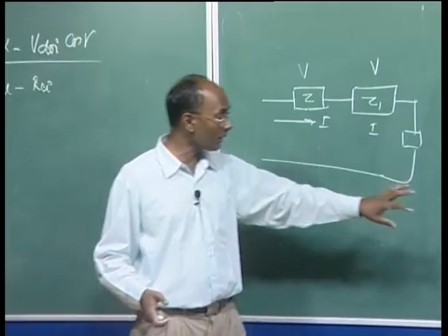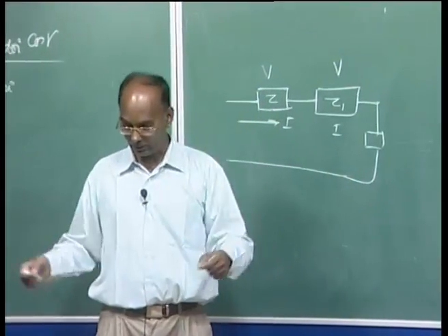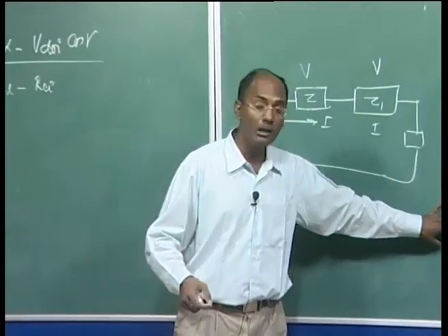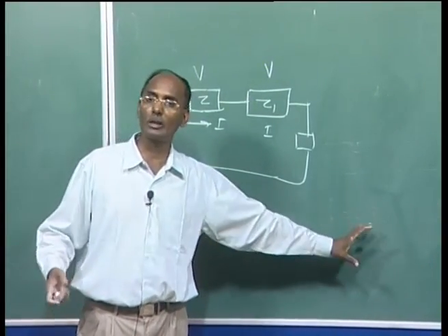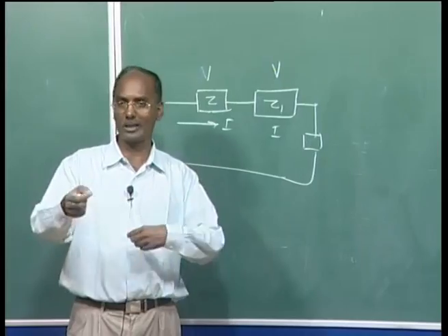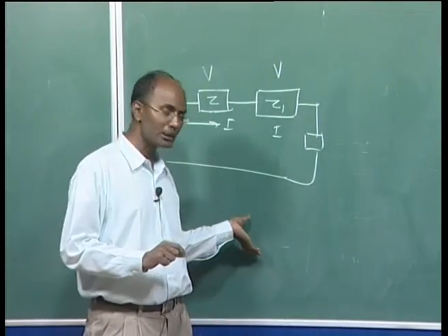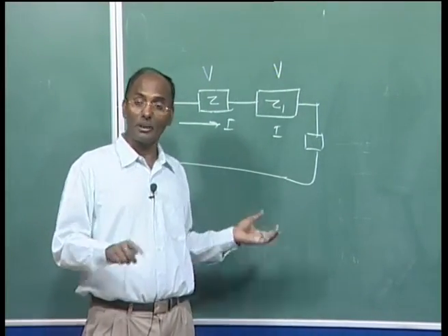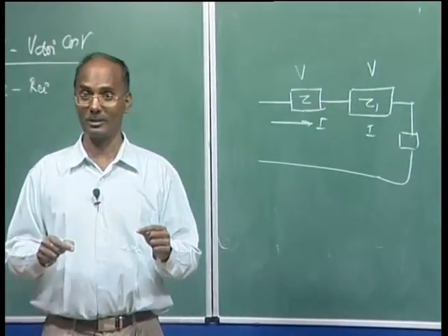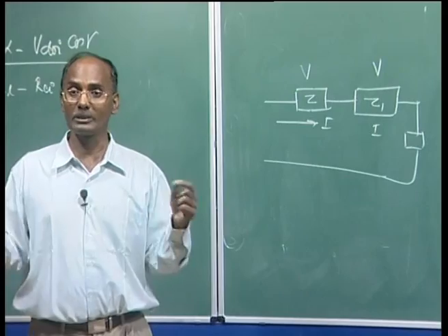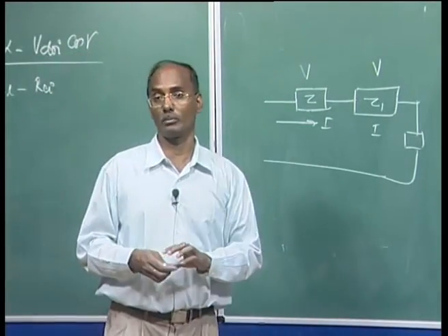But for high voltage, operating at constant current, the losses in the two regions are more or less similar. No doubt the constant voltage scheme may give less loss, but the other thing I said, the fault current, is very important, and based on that we operate HVDC links in constant current mode.